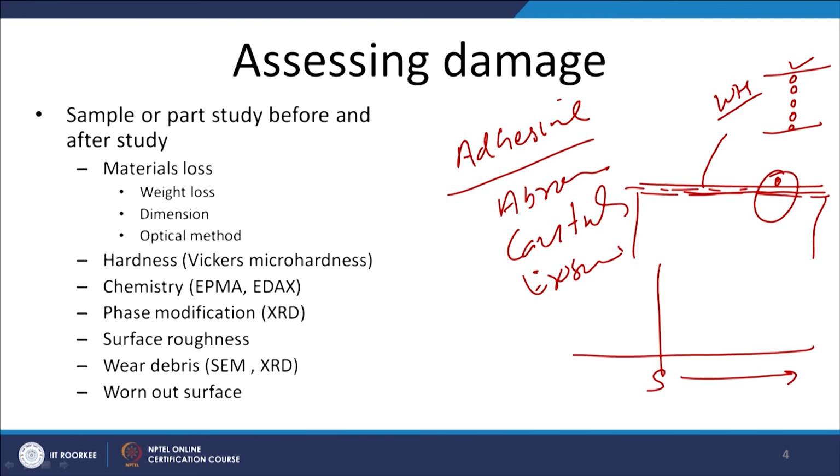So, what we will get basically is hardness on the y axis, which will show that there is a higher hardness at the surface, and then hardness is decreasing as we go deeper and deeper below the surface. So, this suggests that the near surface layer, up to this extent, has had a significant increase in hardness because of work hardening, and thereafter the extent of work hardening is reducing, and regions further below are unaffected by the extent of surface damage which is taking place.